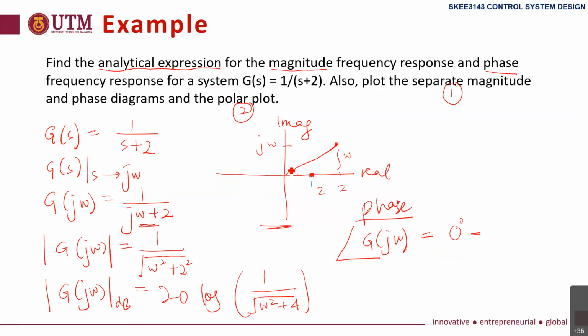The angle here is theta. We know omega, we know 2, so it is inverse tangent of omega over 2. So that is the phase frequency response.